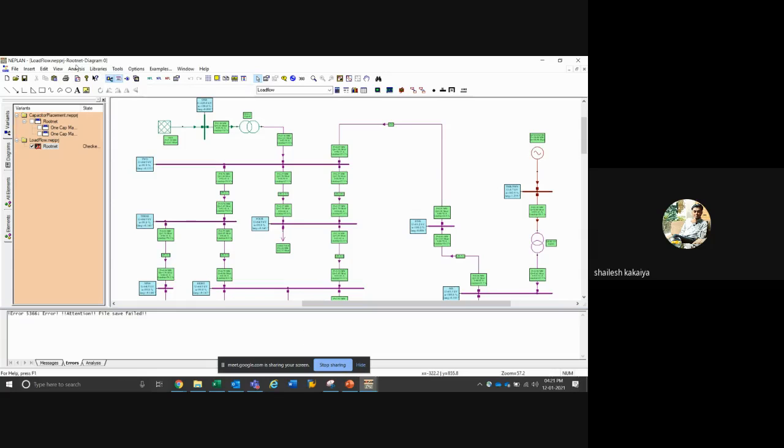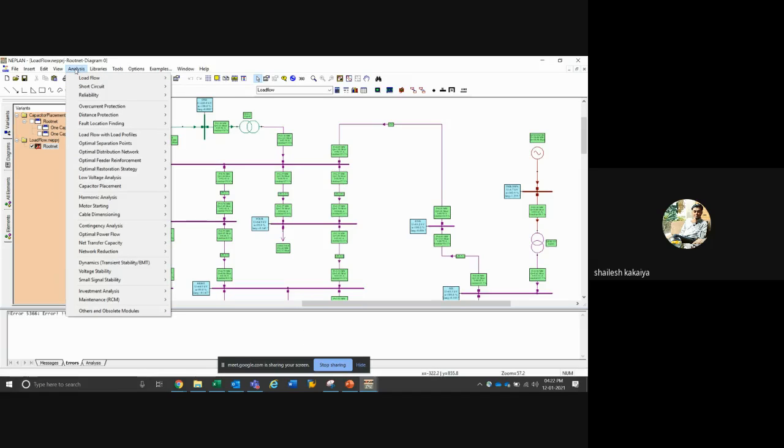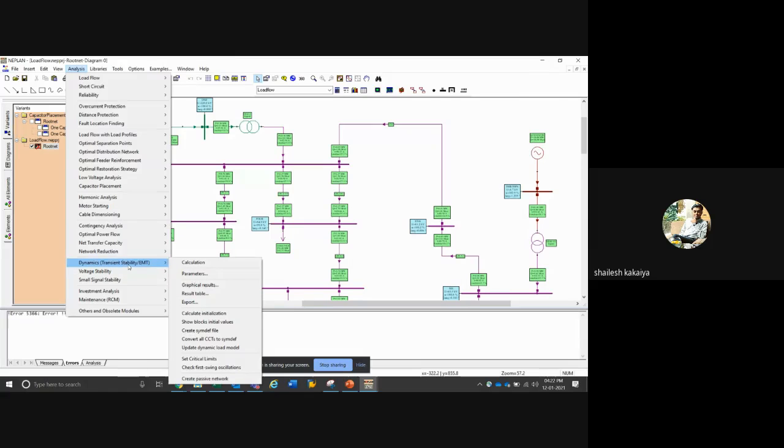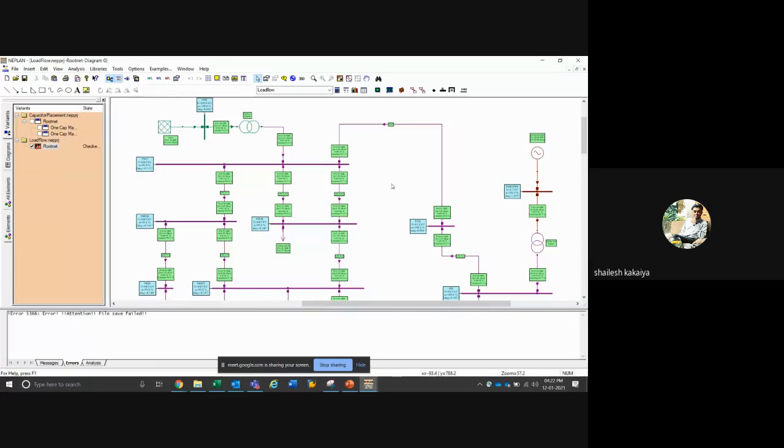And then in the university licenses, majority of the time, the limitation is a node limitation, maybe around 50 or maximum 5,000. Some of the licenses may give more, but not for all the modules. So what we are doing here is for research purposes. We have opened up all the modules. For the university license, you will get all the modules ranging from basic load flow to transient stability for unlimited nodes. That means there's practically no node limitation, and you can simulate any larger network, support any state utilities or discoms in pilot projects, start helping out people and take on practical problems.